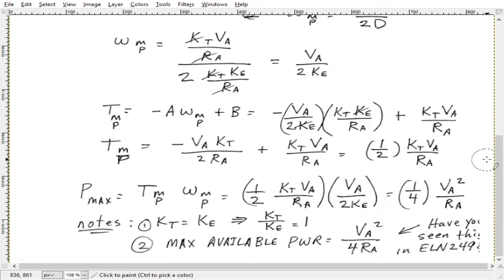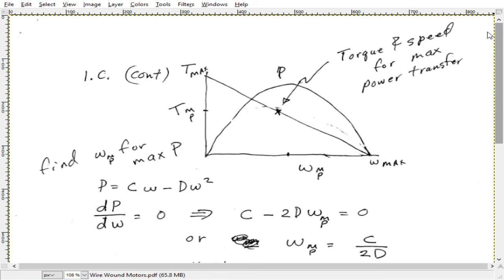All right, go up to the top here. So wow, there's my power curve. So here's the torque speed, and here's the power curve. Okay, now this equation has torque for the vertical axis, but the power equation has power, and so I should have probably drawn a vertical line here for power, but this is the peak power. So at this speed, which I'm calling omega motor peak, and then torque motor peak, produces the maximum power here.